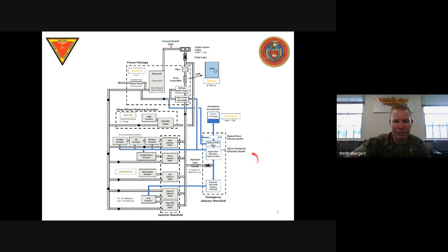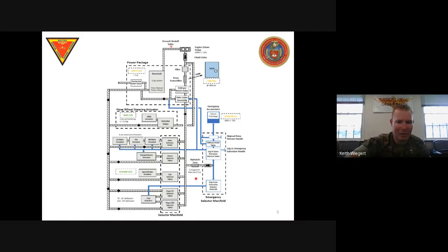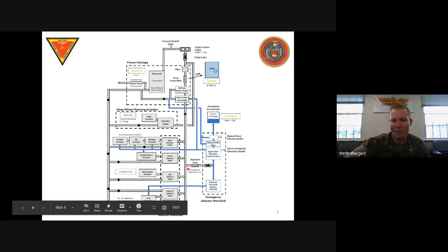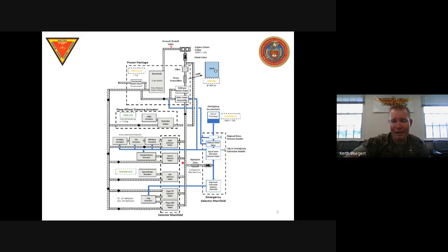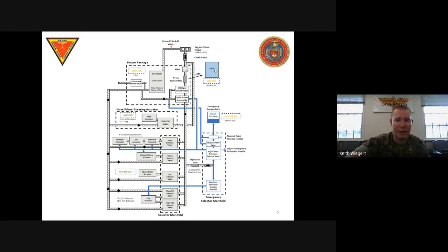If it leaks on the emergency side or if it leaks on the main side, the hydraulic fuse will close, hopefully saving one of these sides, right? Remember, it's going to detect the leak if it's greater than 0.25 gallons per minute with a max loss of half a quart, right? So that's the numbers associated with that. Then we're going to go through a one-way check valve. Once the main side sends fluid to the hydraulic side, it stays on that hydraulic side and it stays at that pressure until we need it or we shut down the plane, right?